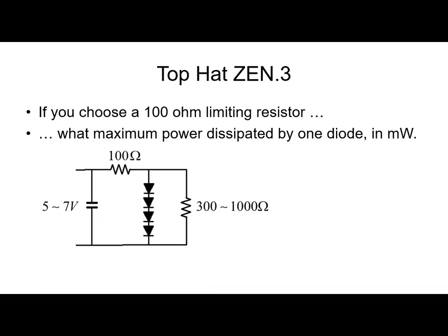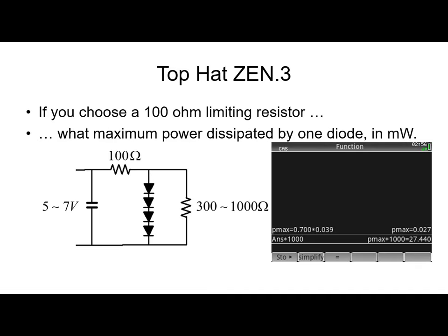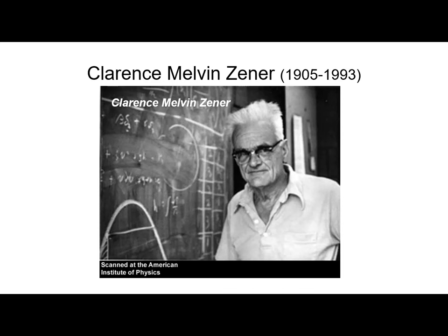This technique can work and has worked and has been used. The catch is that we have to use a significant number of rectifying diodes to achieve what we want, to keep the voltage and the load constant. It would be better if we could have a single device that does the same thing. Bell's laboratory, using the research of Professor Melvin Zener, designed a new device.